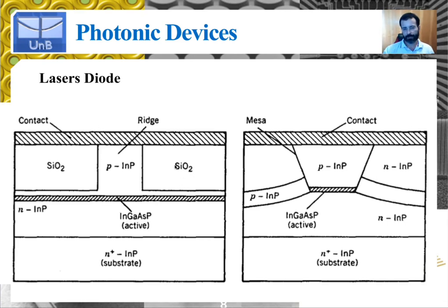This oxide layer, silicon oxide layers here are just dielectric, so you have no current flowing through these lateral dimensions here. The current would flow through the device here, and as the current flows here, because of the increasing carrier concentration, you have automatically an increase in the refractive index, which is another effect that also happens and contributes to light confinement, right?